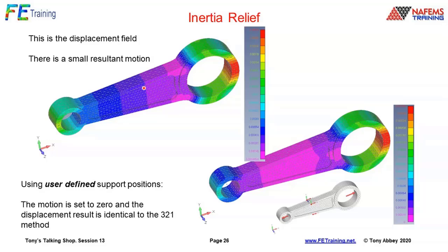What you've done then with the symmetry boundary conditions, which are constraints, is you've actually put in a fully constrained model, but those constraints are physically meaningful. Those constraints become the cut face constraints, stopping movement across the plane. Unfortunately we can't apply a symmetry plane down the middle here, we can only get 2 planes of symmetry in here, so we're still stuck with 1 constraint.